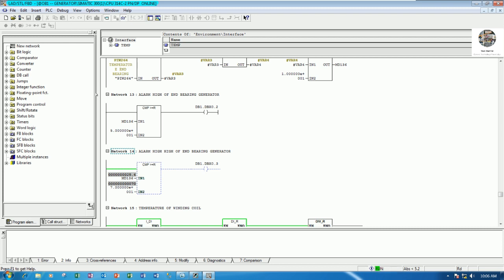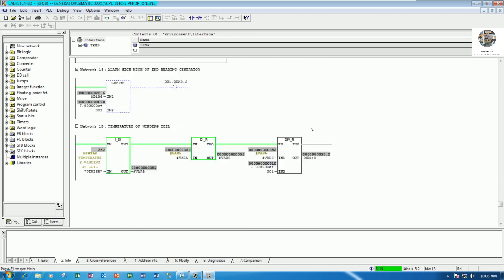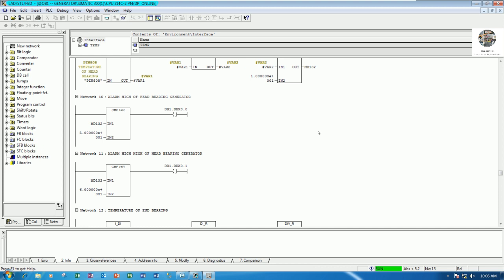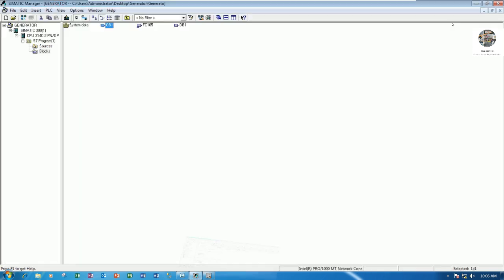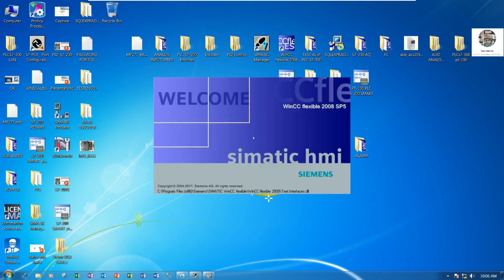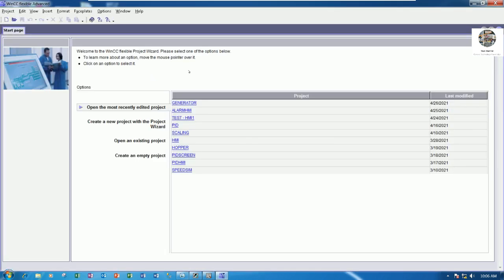And we need to create the alarm on WinCC Flexible, right? So let's go create the alarm on WinCC Flexible. So open the WinCC Flexible software, and then I will use the existing project that we already learned in the previous video. So the project name is generator.